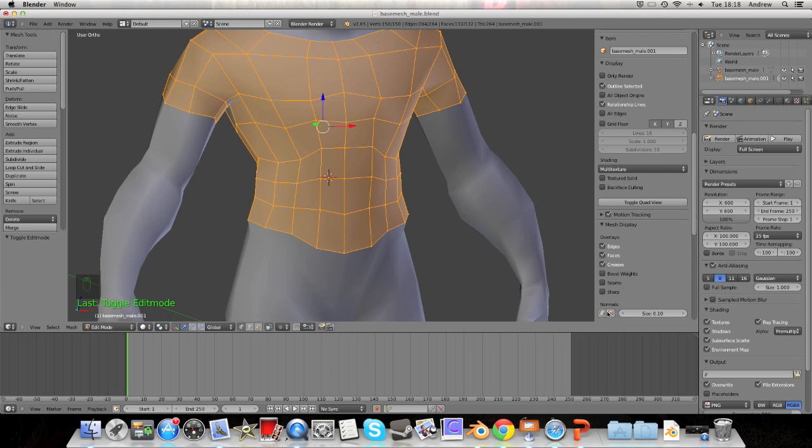display the face normals, and we'll see that they're all pointing outwards. Basically it's to do with texturing and things, and they need to be pointing outwards for it to be visible in a game engine, and it also causes a few more problems if they're facing in different directions. So they've got to be all facing outwards, but the fact that they are all facing outwards individually from their faces means that we can scale along them. So just like you would scale along the X, Y or Z axis, we're scaling along the normals individually, which means it's going all outwards.